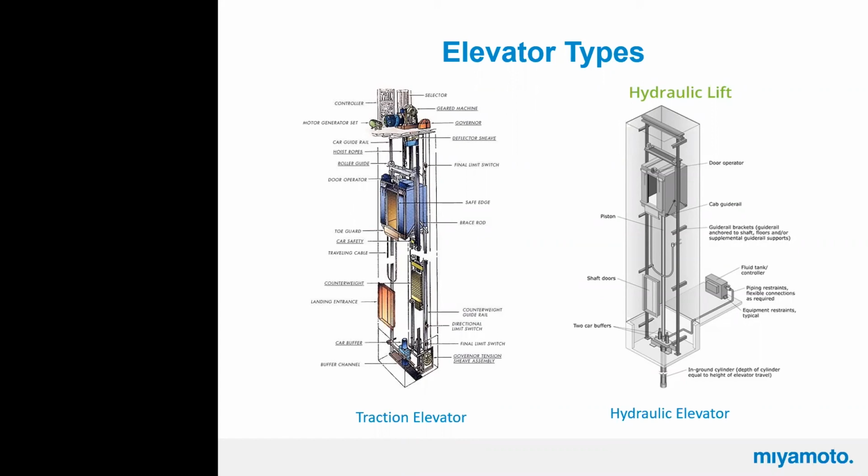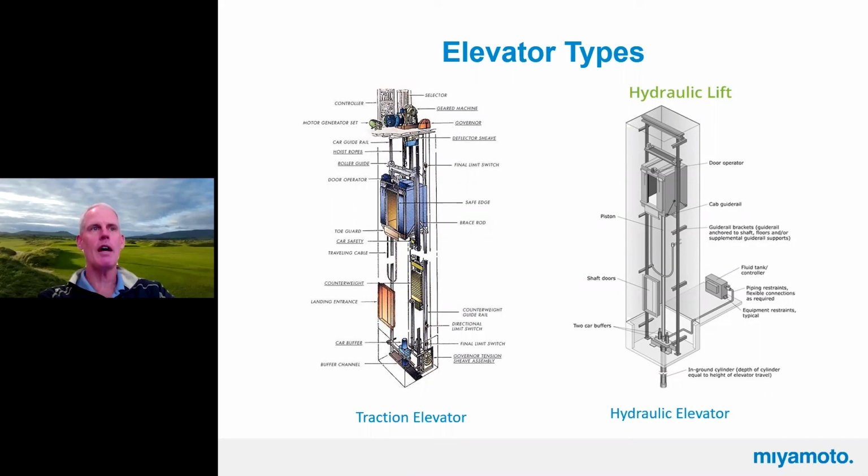Hey, Jeff, did you have just the steel guide rail support posts, or was there an entire steel frame? We had an entire steel frame on that one. Part of the reason was we didn't really have enough diaphragm on one side to kick the reaction in, so we put a steel column in each corner of our rated wall assembly and an HSS tube around the assembly at each floor level, at the floor and the roof. Then the guide rail supports attached to those.